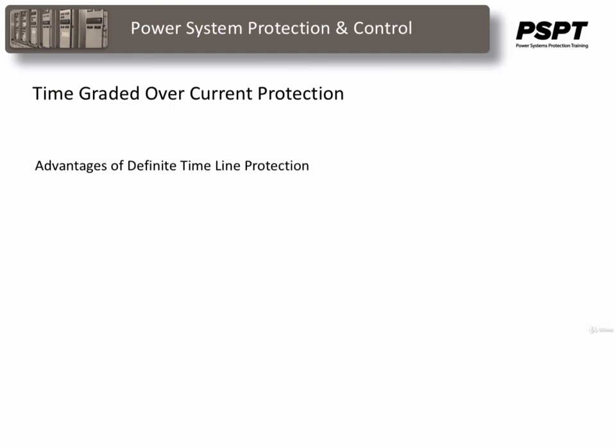There are, of course, advantages and disadvantages to this type of line protection. The main advantage is, of course, its simplicity. The second major advantage is that during faults, only the nearest circuit breaker to the fault, and that's the farthest from the source, will operate to isolate the specific portion of the line that has the fault, resulting in the fewest number of customers being interrupted.